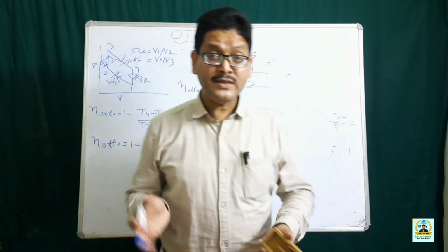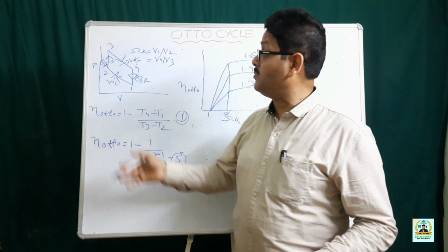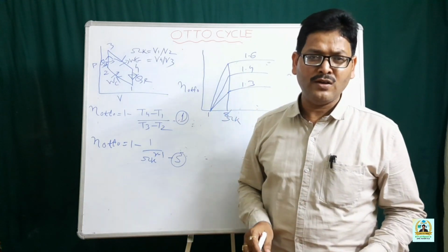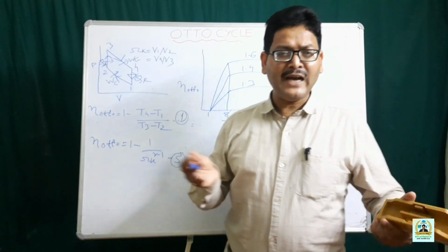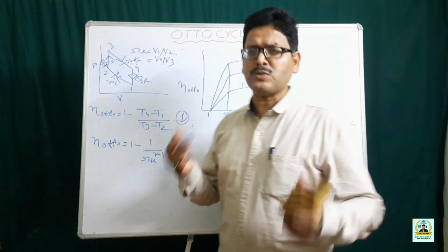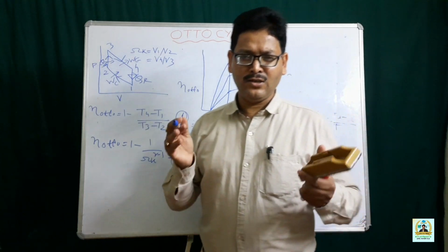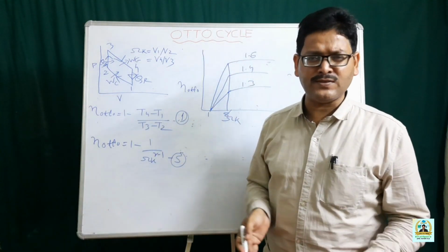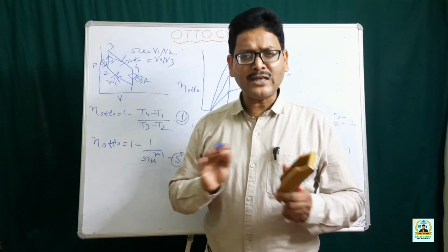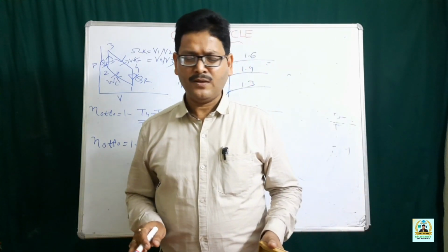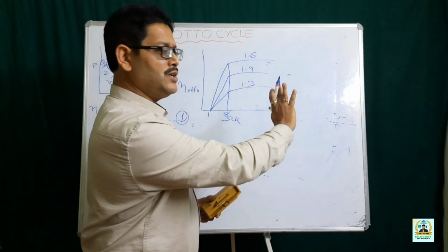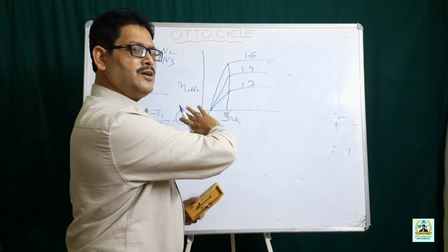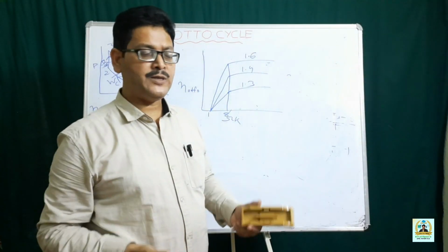So usually what this tetraethyl lead does when it comes to improving the performance, it reduces the engine knock, and usually 1 part in 900 parts of petrol is being added, but that is not being followed in most of the countries. There are few exceptions, like countries like Iraq, then Afghanistan, North Korea. There are few countries which are still using this, but it is not at all being used in most of the countries. Now, for that reason, there is a limitation to which we can improve. You can increase the compression ratio to improve the efficiency.